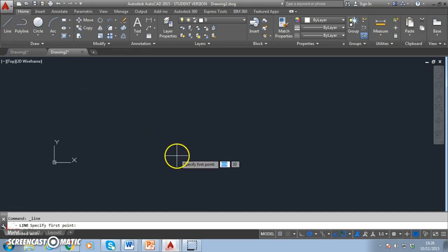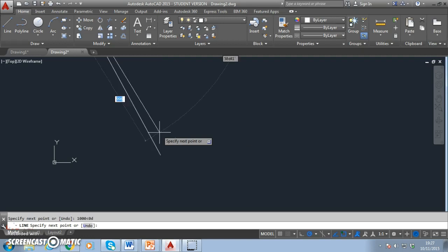And now when I go to click in, if I put in a distance, 1000, and put in an angle of say 0, that should draw a line straight up. Okay, just 1 second there, I'll do that. So I click on my point, my first point. I'll put in a distance, which is 1000, which is a meter, and then angle, and 0D, enter.